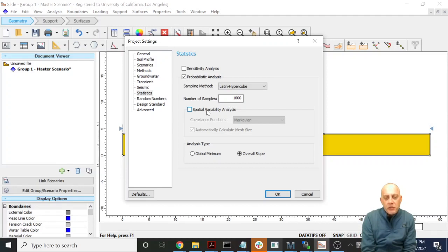It turns out that probably what you're measuring is actually spatial variability rather than uncertainty. Uncertainty would be how well do you know the undrained strength at a point. And to get that, you would have to sample the same point over and over again and do a bunch of lab tests to figure out that distribution. It'd probably be pretty narrow bands. You'd probably get a pretty small standard deviation. So anyway, I think a lot of the time we mix uncertainty with spatial variability, and those are different things.